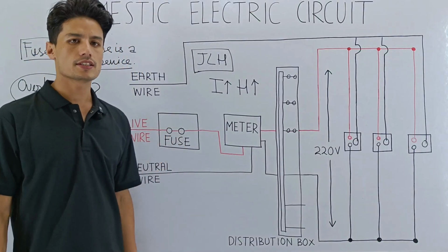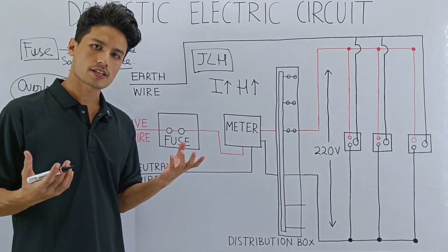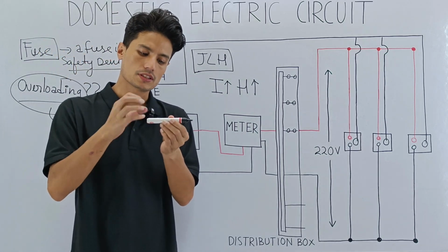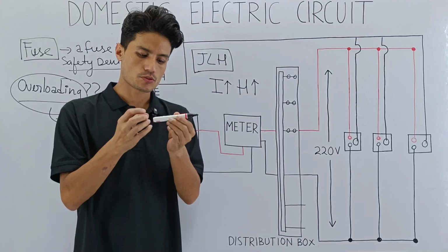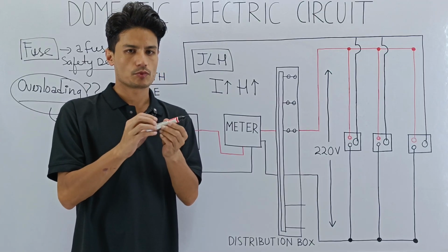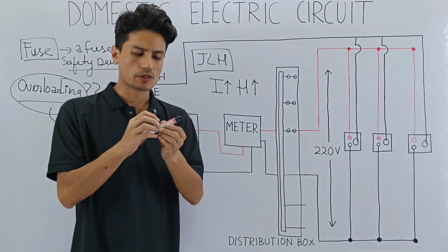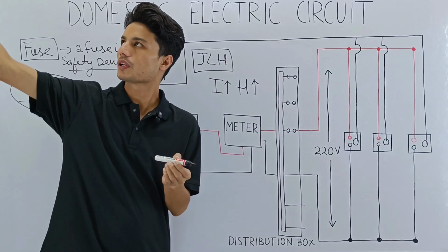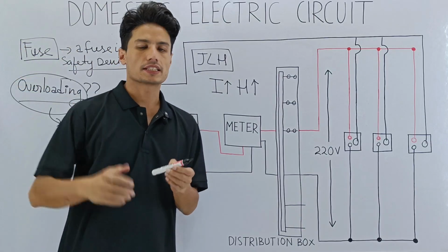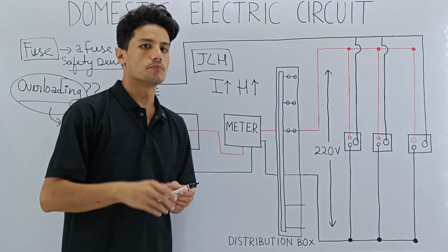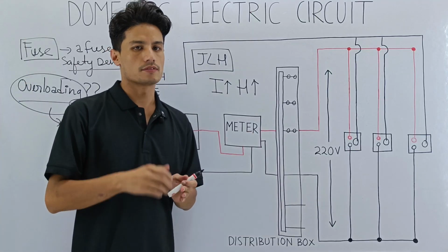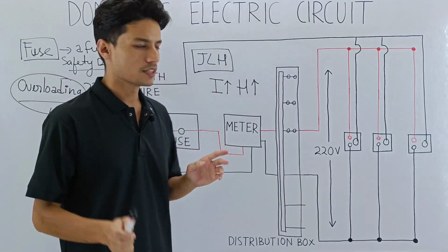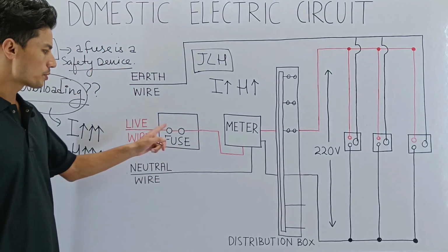Now, what will happen if the wires get overheated? Danger, heat danger. Why? Because the insulation upon the copper, the insulation upon the aluminum, which is nothing but plastic, will melt and it may even catch fire, and the whole electrical circuit, the whole plastic casing running through our rooms and houses, will get burned. So do you want this to happen? Of course not. So overloading is bad.